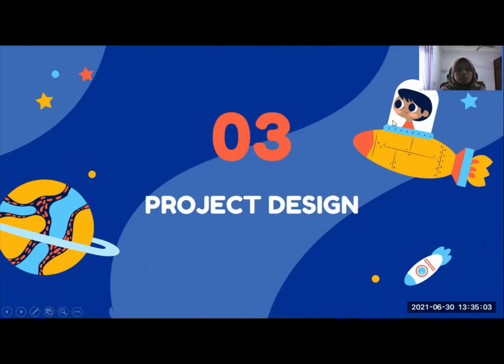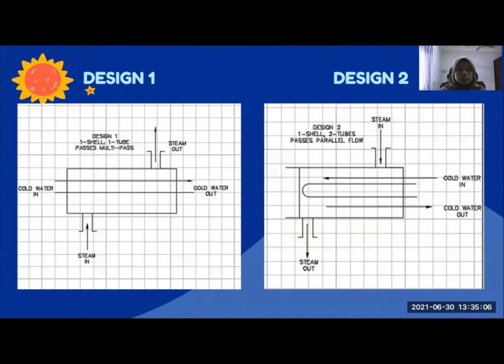Okay, my name is Hanina Zikaminta Harun Rashid, and next I'm going to present on the project design. We have proposed 4 designs. The first design is one shell, one tube pass multi-pass, where the steam will move through the shell from the entrance and exit at the bottom and top of this heat exchanger, while the tube will be passed through by the cold water. For the first design, it will move just in a straight line. And then the second design is one shell, two tube passes parallel flow, where the cold water will enter and make a U-turn and go out from the same side.